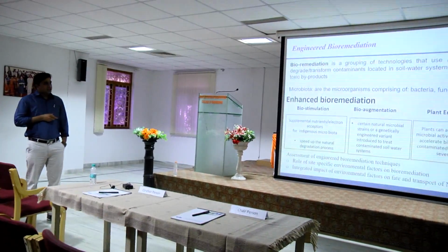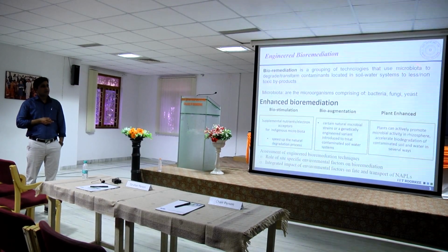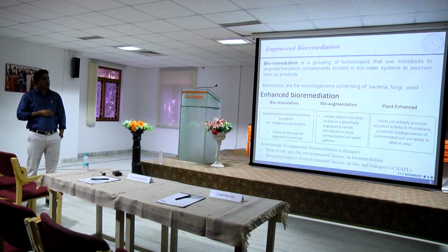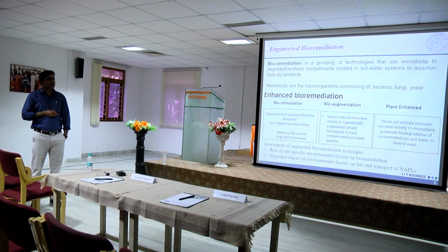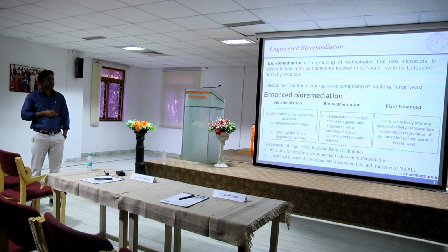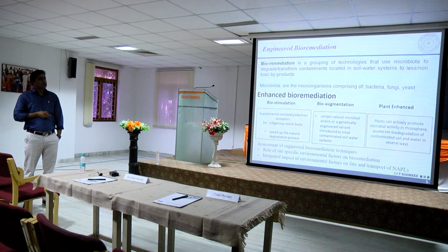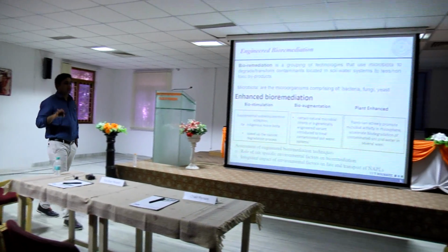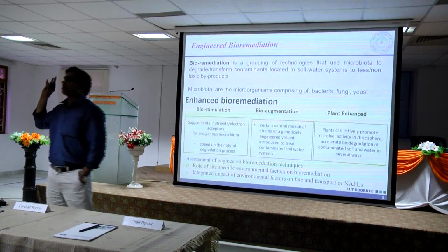So bioremediation is a grouping of technologies which uses natural microbiota to degrade or transform the pollutants. These pollutants could be organic or inorganic type. Just now we are talking about the LNAPL, DNAPL, which are organic type of pollutants, which could be located in the soil water system, to less or non-toxic daughter products or byproducts. So in bioremediation, natural microorganisms are utilized for eating the contaminant which is there in our natural resources.